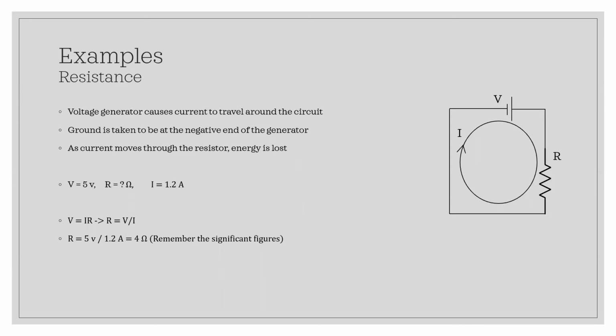And then the voltage example. Same setup. We don't even have to rearrange Ohm's law this time. Voltage is already equal to resistance times the current, and we're given 1 kilo ohm and 0.2 milliamps. Multiply them together and the voltage across the circuit is going to be equal to 0.2 volts.